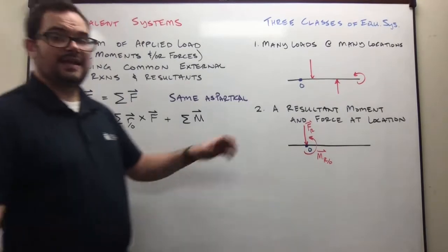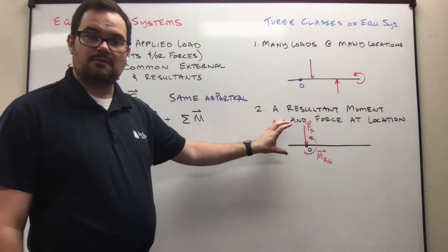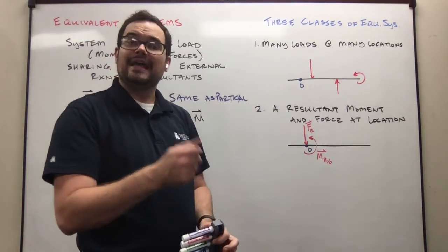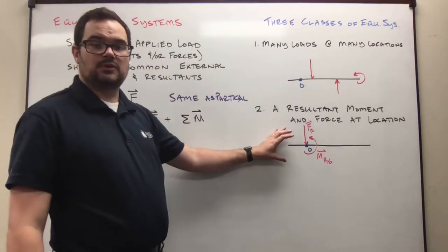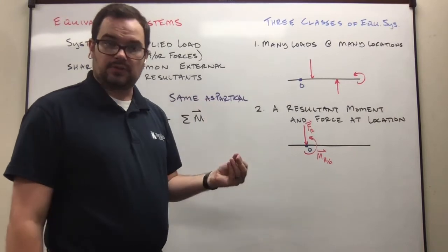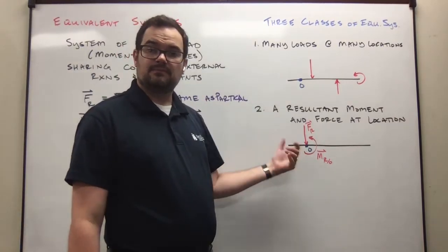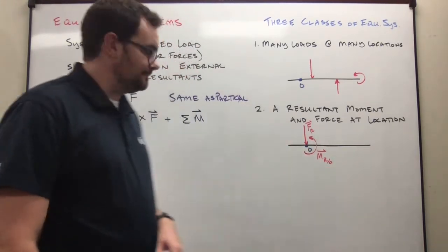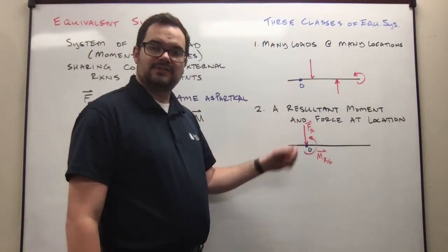Okay? So the idea here is that I'm simplifying the many complicated loadings into one force and one moment. This is equivalent to having all of our forces and turning it into the resultant force, an equivalent system of a single force being applied at a point. It's exactly what we're doing here. So we're bringing together that idea of equivalent systems from particles, resultant force, pulling on it. We're bringing in the idea of equivalent moments. Free vector can be applied anywhere, although this is about a particular point, right? About a particular point. And our resultant force.